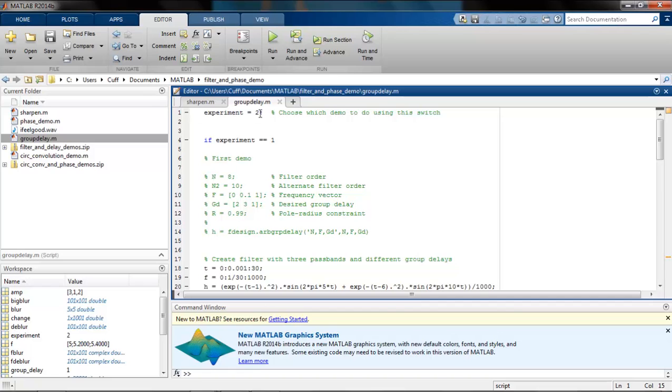By envelope of the sound, I mean if your signal, it doesn't have to be sound, is concentrated at some location in time or space, then group delay will tell you how that packet of concentrated energy will be delayed forward or backwards in time, depending on its frequency.